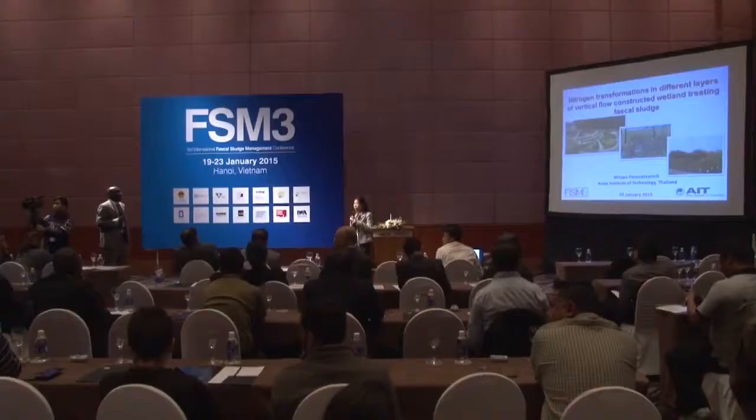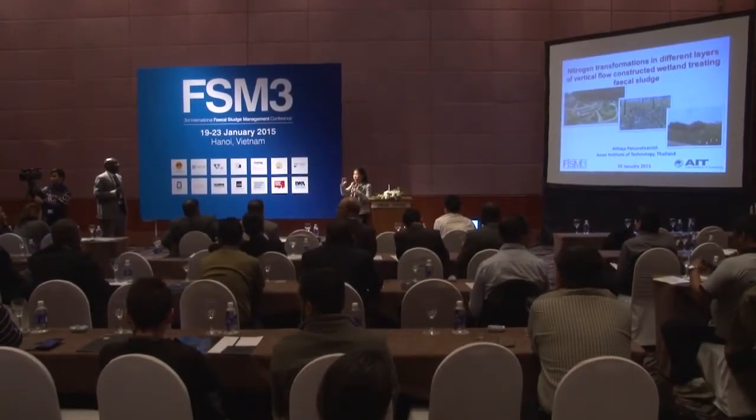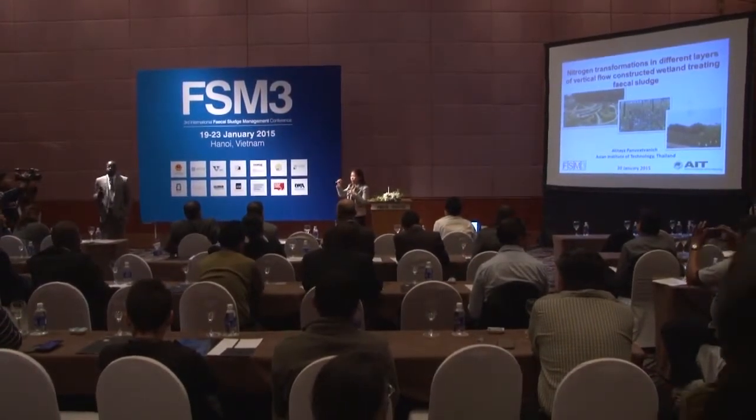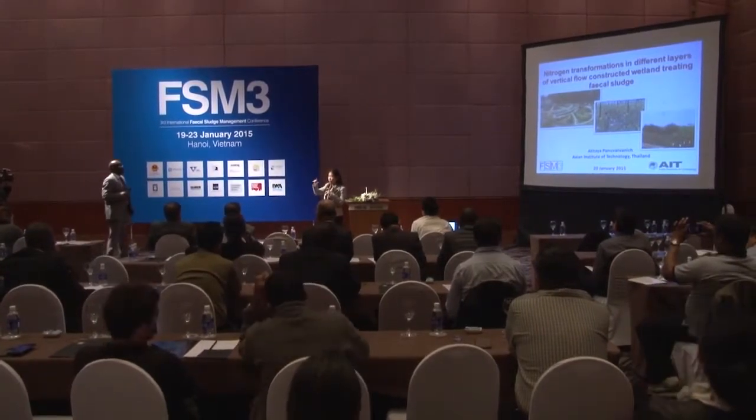Have you studied the effect of depth of different media on the transformation efficiency? Can you increase the transformation by increasing the depth of the gravel layer or sand layer? Yes, for the sand layer we have about 15 centimeters, and for small and large gravel about 20 and 20 centimeters. What happens if you increase the depth? Because all the transformations have been expressed per square meter of bed area, not depth. So I was wondering what the effect of depth on the removal could be.